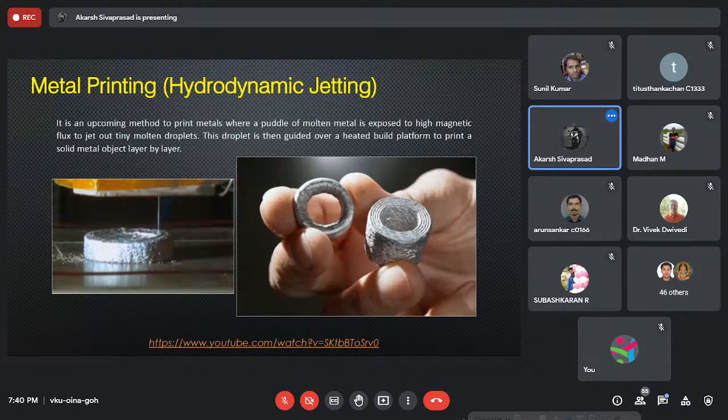So what they started with was they built this really high induction melting heater, and then they passed aluminum wire from a MIG welder feeder through that, and started melting that aluminum and depositing it onto a build platform, and tracing its path, creating a metal object.